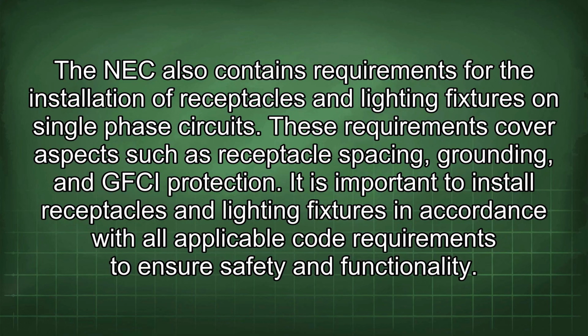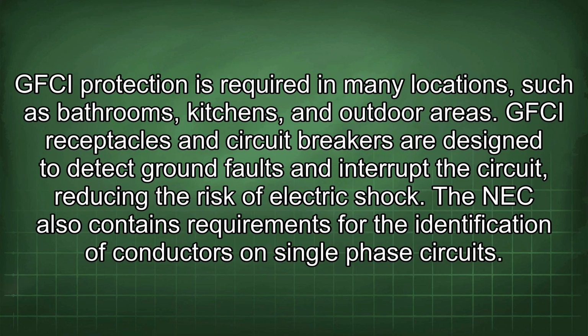It is important to install receptacles and lighting fixtures in accordance with all applicable code requirements to ensure safety and functionality. GFCI protection is required in many locations, such as bathrooms, kitchens, and outdoor areas. GFCI receptacles and circuit breakers are designed to detect ground faults and interrupt the circuit, reducing the risk of electric shock.